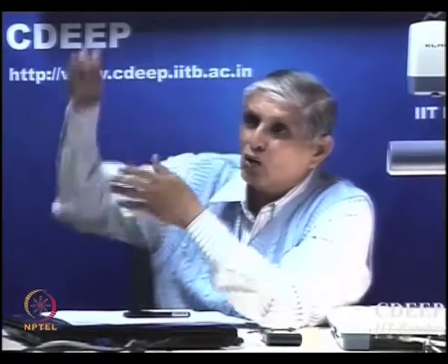Is that clear? The reason why I want that value to be higher I will show you in the small signal case, because I do not want to use that source resistance. If that is smaller, then that RS will hurt me here also. But if it comes, I will use it. It should not be very low because it will then consume power at this gate end, which I do not want. Please remember, the power is not only on the transistor side, but from the power supply to the ground through Rg1 and Rg2 also.